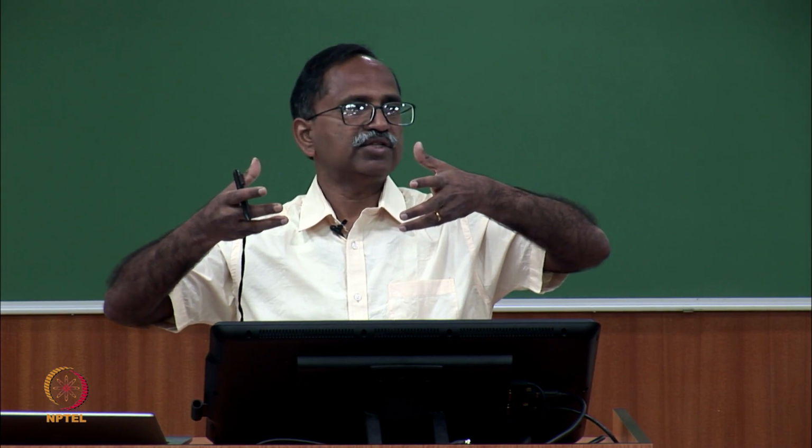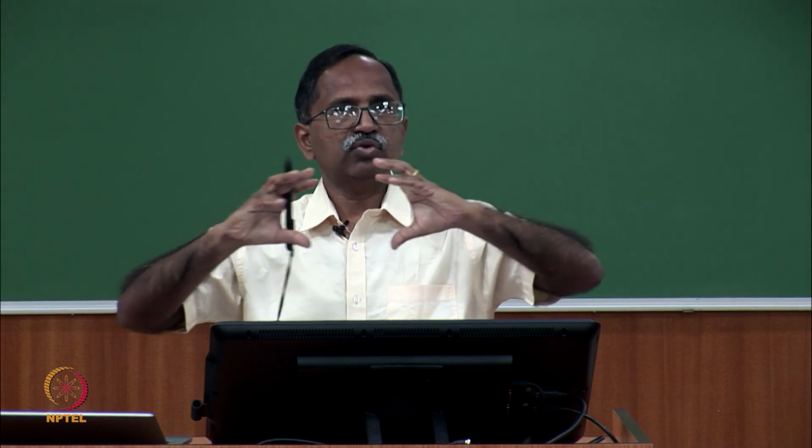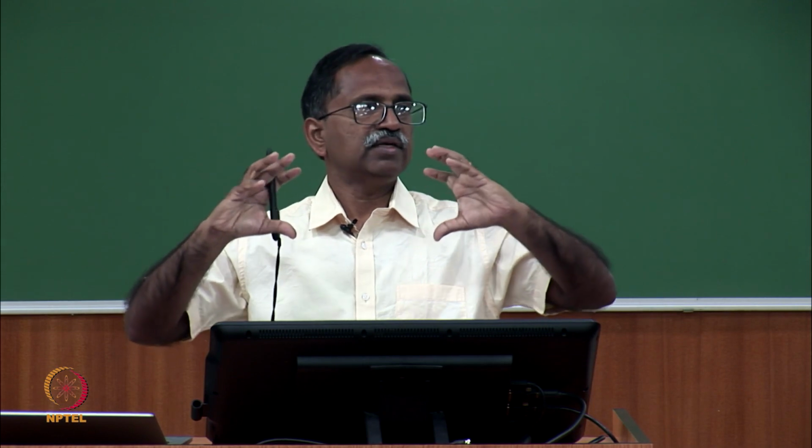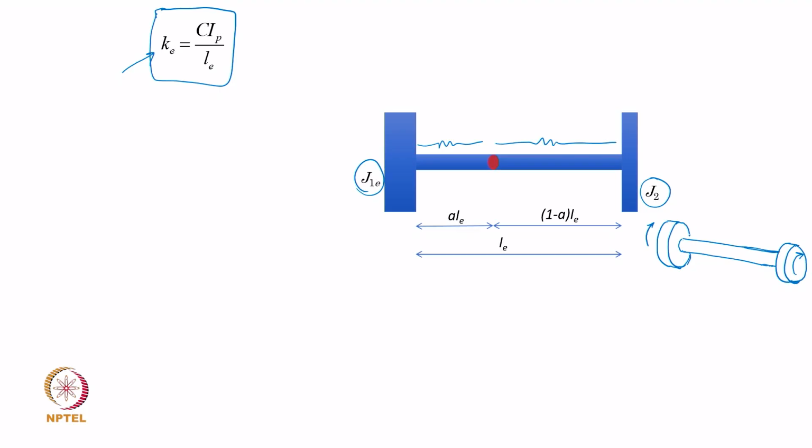Why? Because both the rotors or both these inertias rotate together like a rigid body, or there is no stretch in the shaft connecting these 2 rigid bodies. So, the fundamental natural frequency or the first of the 2 natural frequencies is 0, which actually means that there is no oscillation, there is a rigid body motion. So, out of the 2 natural frequencies, at the first natural frequency which has a 0 numeric value, both the inertias simply rotate.